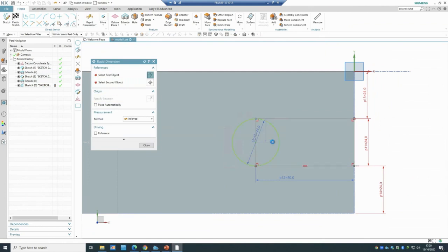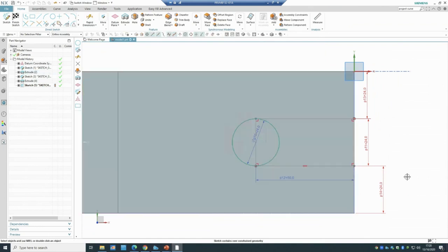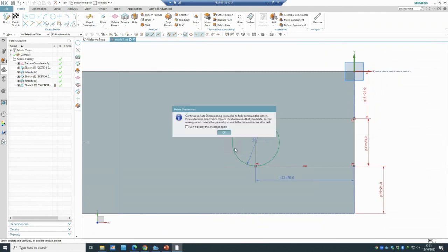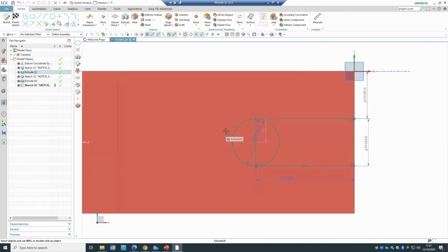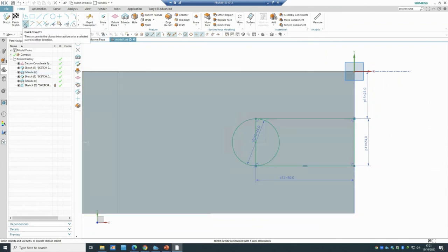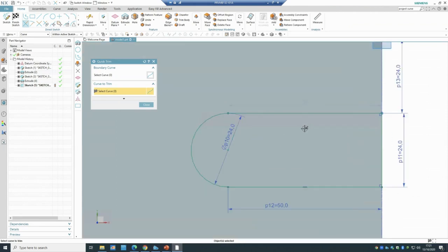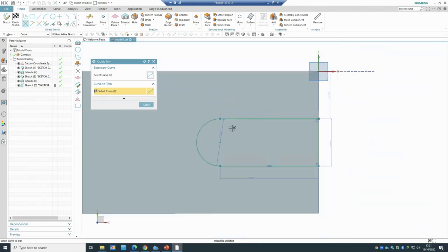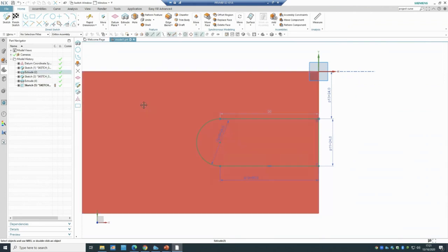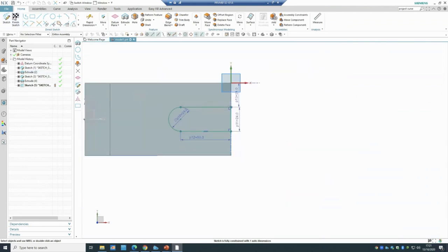So make sure your sketches don't have any kind of red sign over there. It's quite common. I see lots of students make that mistake. Okay, so everything is ready, 50, 24, and now I have to get rid of these two lines. So if you remember how I would be able to delete the lines, it's the trimming. So just go there, get rid of this one, get rid of that one, make sure everything's connected together. Fine, brilliant. That's it. So I finished the sketch.